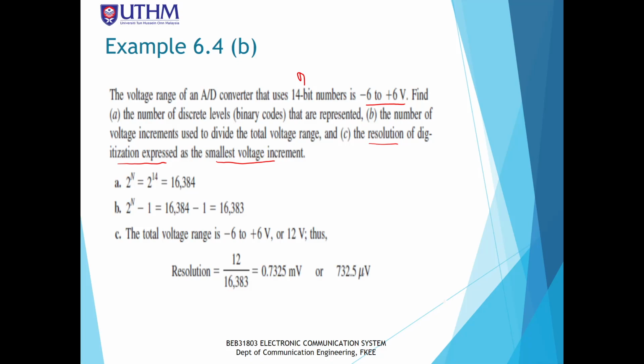Okay, so the number of levels depends on L equals 2 power of n, which is 2 power of 14, because we are using 14 bits. So the number of quantization levels is 16,384.